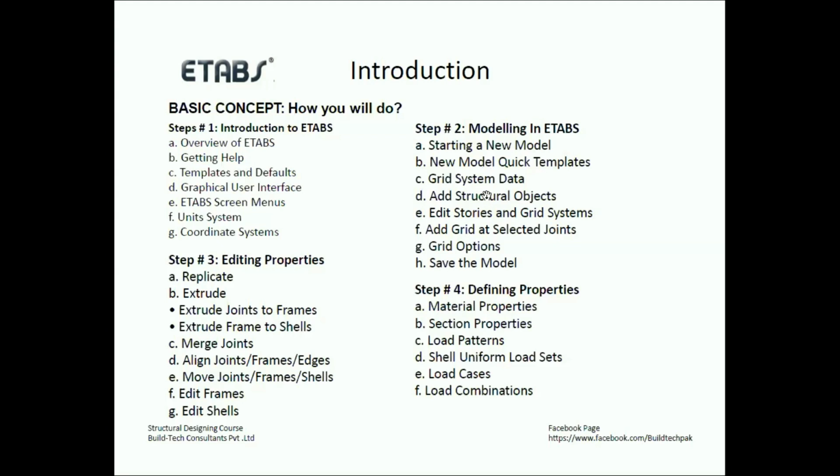The first activity in modeling is that you need to model the grids. Whenever you get a structural design job, you first need to have grids, as completed architectural drawings will come to you. Sometimes you will see the grids passing through columns. The architect has marked columns at some places, and basically he has only marked them, not designed them, and has not even written any size. The purpose of those markings is just to let the structural engineer know that these are the possible places where you can place the columns. In the rest of the areas, please try to avoid putting columns.